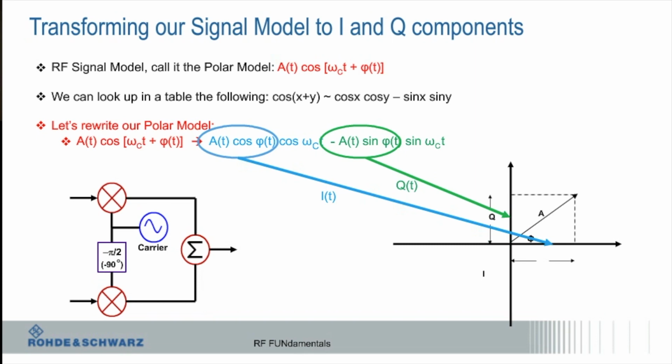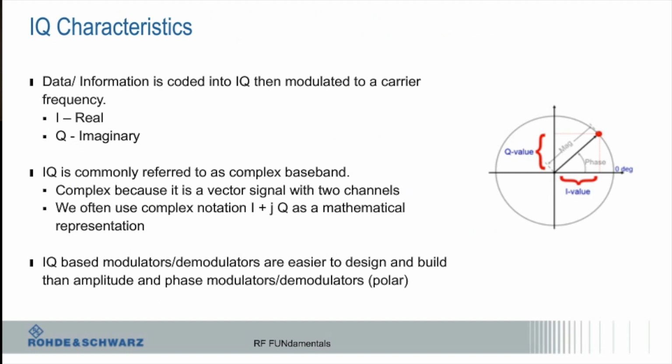That IQ stream is now going to go with the carrier. The carrier is mixing it up directly. This same carrier is feeding both of these mixers at the same time, the only difference being that this one is 90 degrees out of phase from that one. Then the resulting RF signals get combined, and they won't interfere because they're in quadrature.